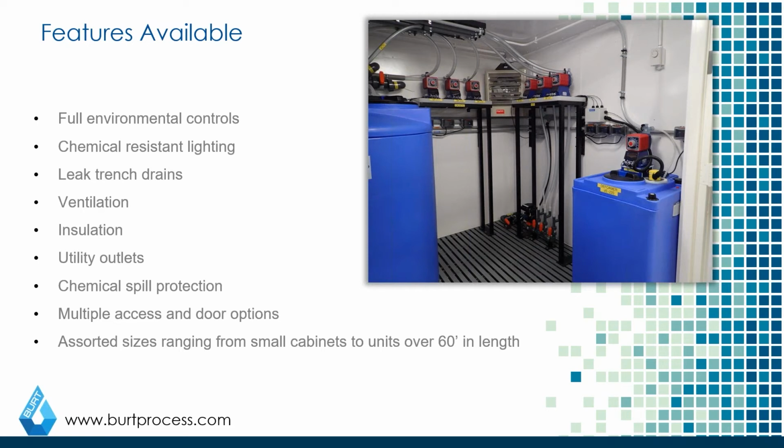They can have large thermoplastic tanks. They're designed for acids and bases, and they're designed for corrosive chemistries. And that's not always practical to be able to insulate, heat trace, and maintain different chemical tanks at different temperatures. Putting this in more of an environmental containerized system is beneficial. It also saves the time on site of having to build, say, an outside building, because you can basically have the entire system built and tested as one assembly, rather than having a skid built and then having a building built and then having to put them together.